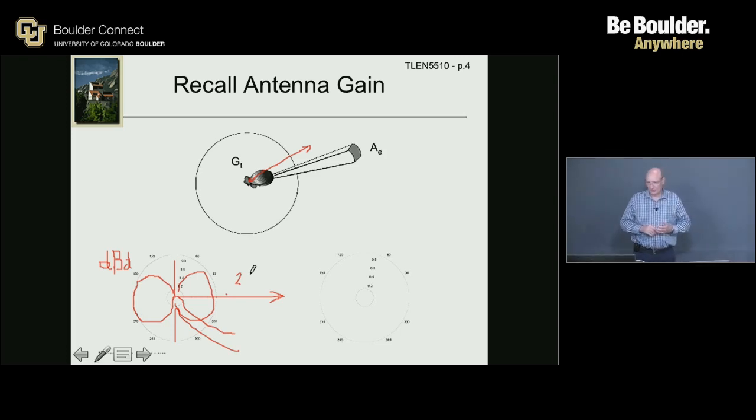So manufacturers like to give the gain in dBi because it looks bigger, it sells better than a gain in dBd. Because if I want to sell you an antenna at 17 dBi or another one at 15 dBd, they're the same, but the one at 17 dBi sounds better. Plus, it's silly to compare to a dipole. Comparing to isotropic makes sense. It's just some people didn't like to do that because an isotropic antenna doesn't exist, so they wanted to compare it to something that exists, but never mind.